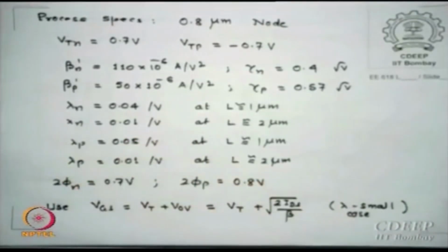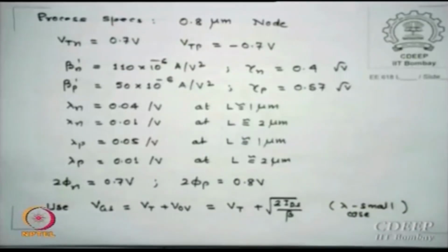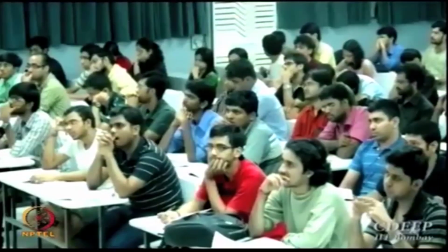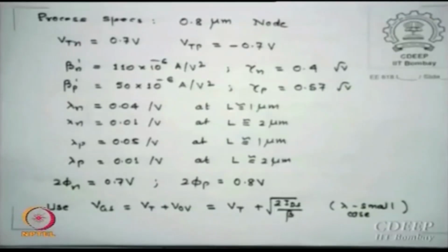You go see full model files, not necessarily in the NG SPICE you have, but the level 9 BSIM models will specify what max min it will go through. In our case we choose one of the values, but in simulation it should figure out what it is and solve. So in real life these values are chosen by the program and not by you, it will actually pick up the value.